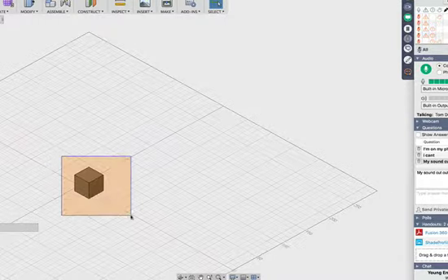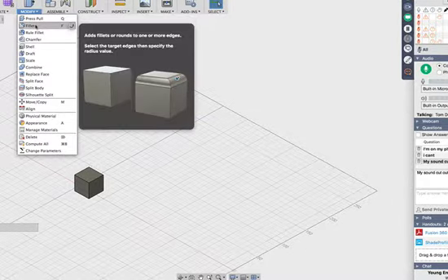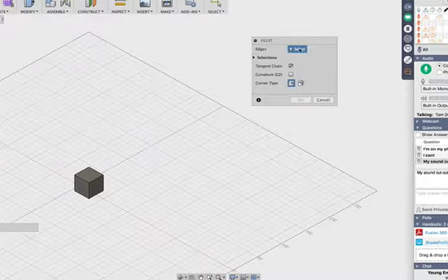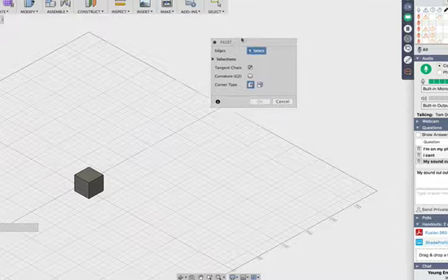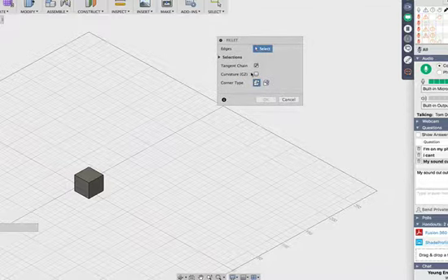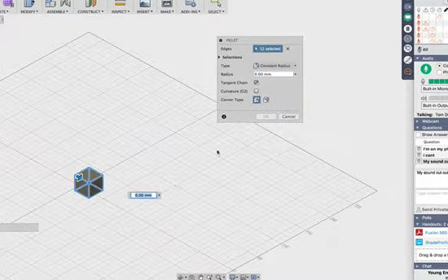So if I grab this, all right, so there's my box. I'm going to modify, fillet, or F. It says, remember, use these menus and follow the order. It says select the edges. We're not worried about tangent chain, but let's first get the edges. So I grab this whole thing. There are all the edges, and it says, well, hey, what do you want to make this?